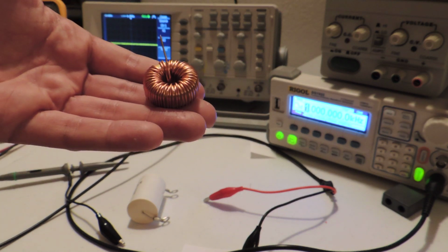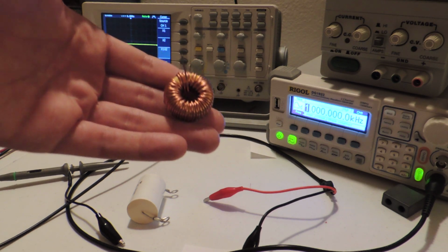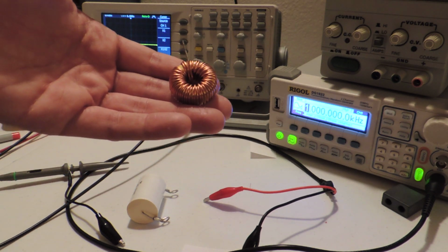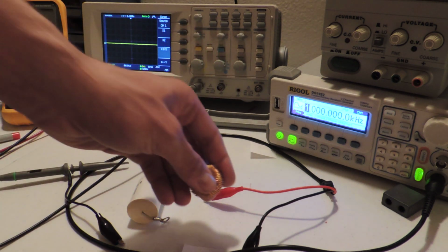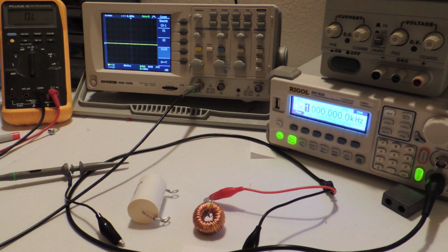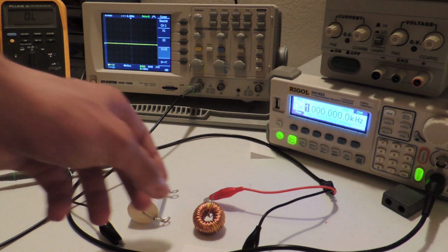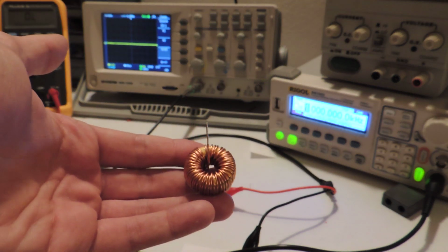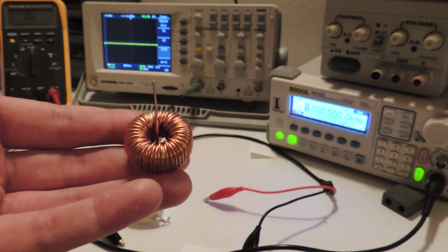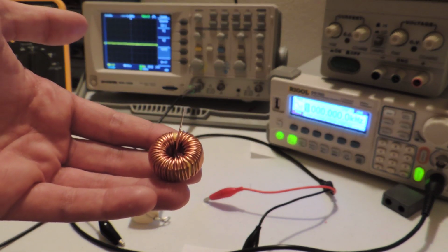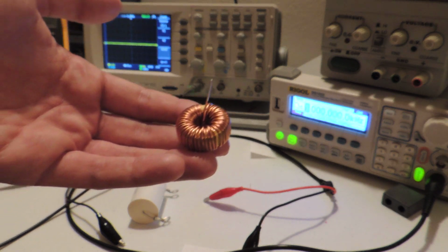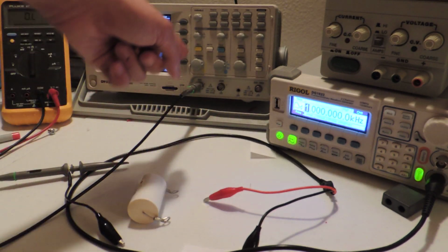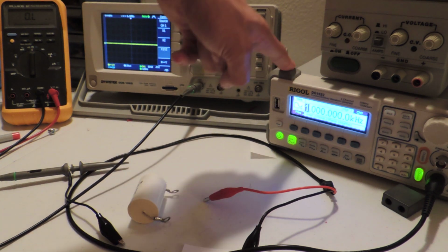Normally the way that we go about measuring the value of an inductor is with an LCR bridge. However, most LCR bridges are incredibly expensive, usually on the order of a few $1,000s. They also measure the inductance over a wide range of frequencies, usually from DC all the way into the megahertz range. However, for most hobbyist applications, we do not require this level of precision, and therefore we don't need to spend this sort of money on an LCR bridge. So what I'm going to show you today is a method of measuring inductors relatively accurately, to within 5%, using only your scope and your signal generator.